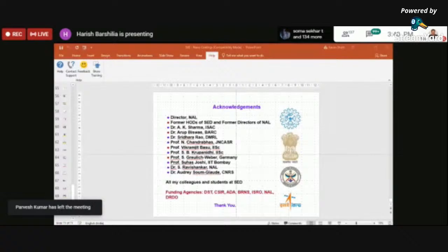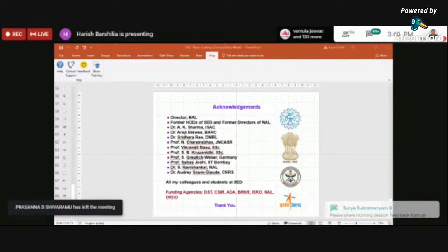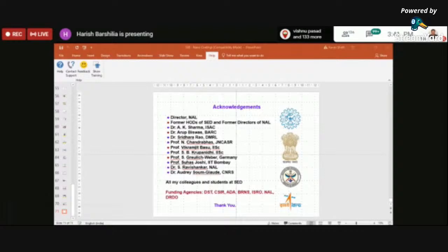Sir, please tell me the novel ceramic coating for Ti6Al4V by magnetron sputtering technique to improve sliding wear resistance. Well, I understood. You can do two kinds of things. For Ti6Al4V, you can directly do plasma nitriding. You will get all the properties: corrosion resistance, mechanical hardness improvement, and wear resistance. That is one way of doing it.